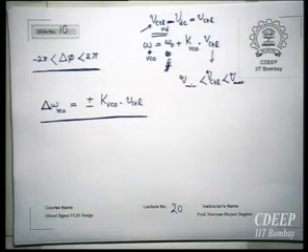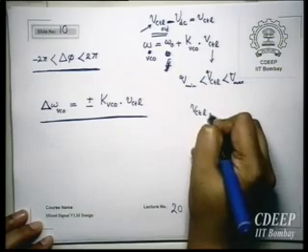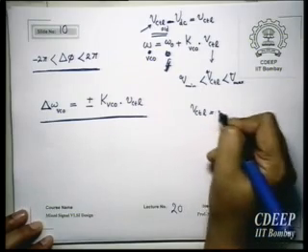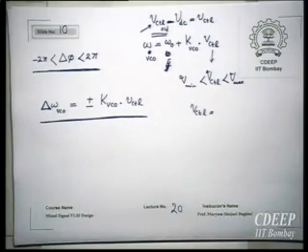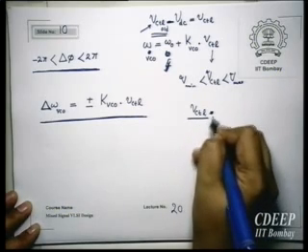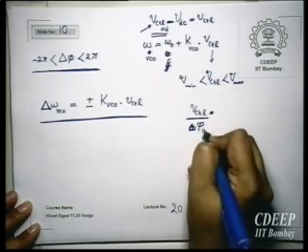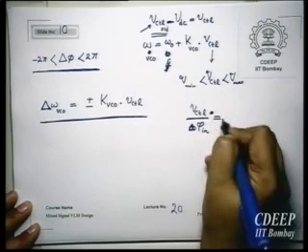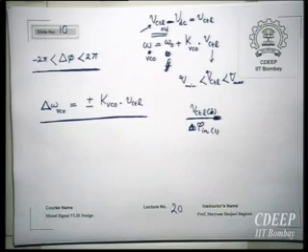And then VCTL, essentially the value of VCTL that I can generate, is a function of charge pump, right? I can write VCTL, for example, on phi in. This also will have a transfer function, right? Again, it was a second order transfer function.